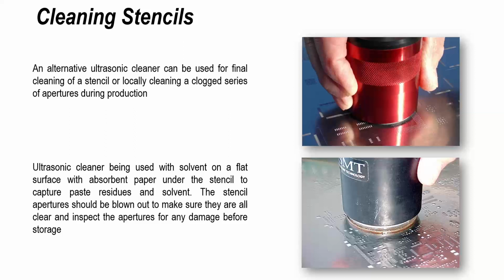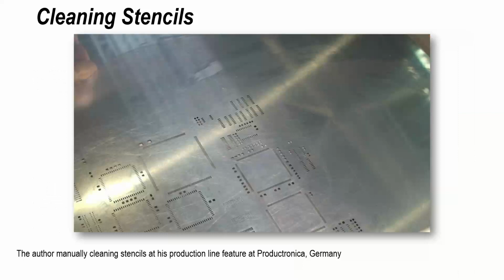And then you've got manual but ultrasonic cleaning. And there's a couple of suppliers of this type of equipment out there. And what we're doing is introducing solvent to the stencil after you've cleaned the majority of solder paste off of the stencil. You're not starting just from, as soon as you've taken your paste to reuse on another job off, you take the majority of it off again with a squeegee blade, but it's just taking it and cleaning the surface and removing it from the apertures. So this is just an example of ultrasonic handheld tools. But again, the chemistry you're using needs to be right for the process.